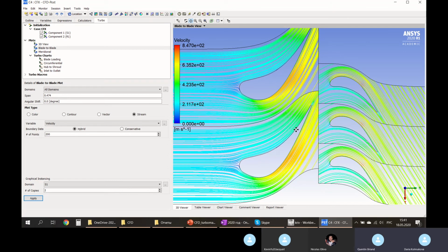Too low values of efficiency could also tell us about some problem in the flow inside the turbo machinery, so we need to go carefully through the flow structure again. Also a criterion could be comparing CFD results with the results of your gas dynamic calculation. There should not be a great difference between these values, I mean, using analytical formulas and CFD calculation.